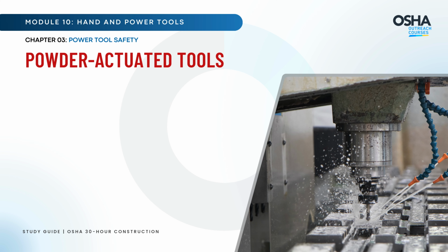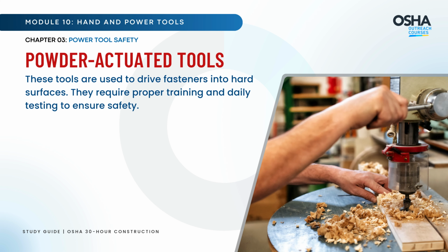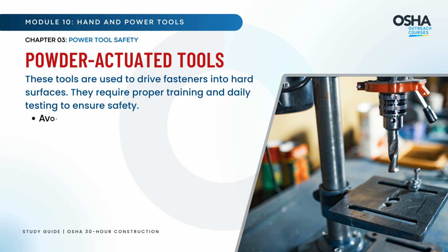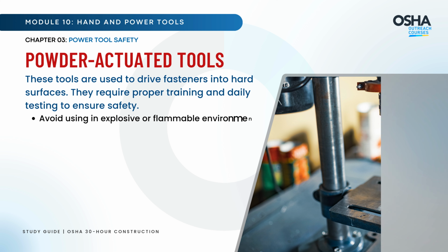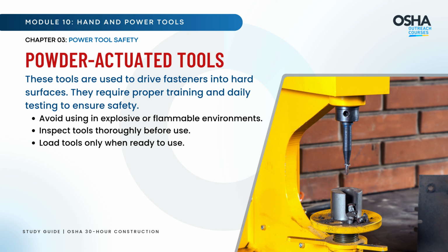Powder-actuated tools. These tools are used to drive fasteners into hard surfaces. They require proper training and daily testing to ensure safety. Avoid using in explosive or flammable environments. Inspect tools thoroughly before use. Load tools only when ready to use.